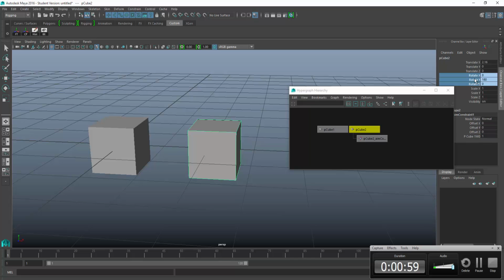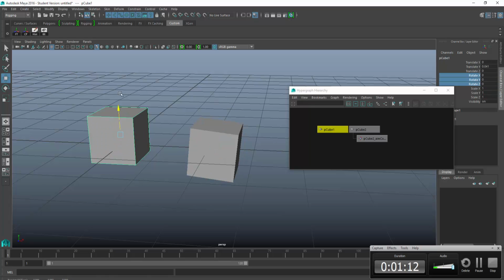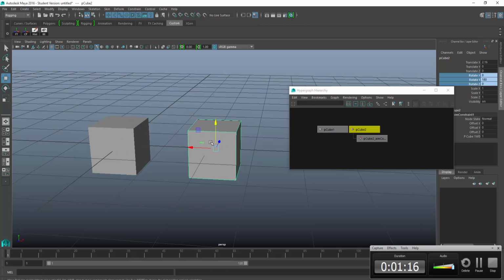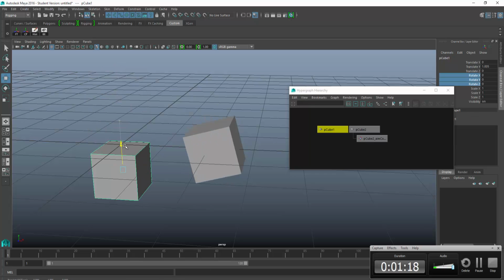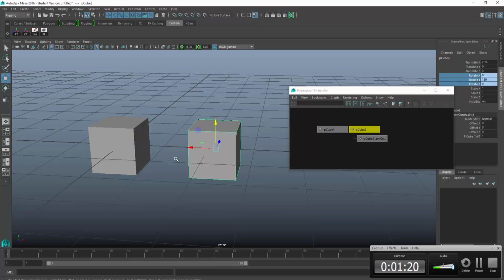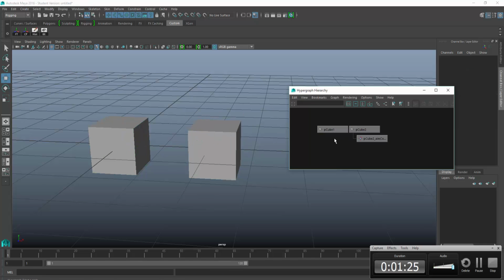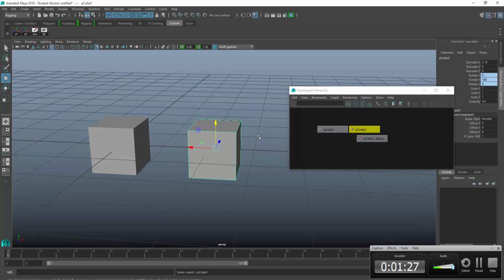So setting keyframes on this by selecting the cube and rotating it would really kind of mess up the connections that are happening. We would have overlapping or conflicting connections because this cube is the thing that controls those rotations. So in order to have something that we can control the rotations of, but at the same time still be able to animate, we could use a grouping system for this. So let me do Control Z to undo to get back just to the two cubes.